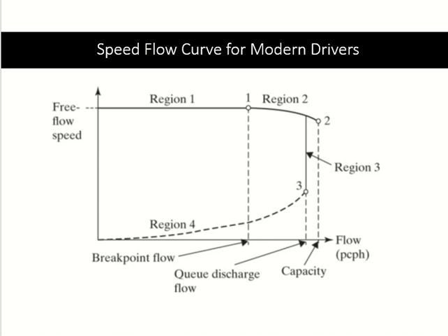To solve this issue, to make it much smoother, I don't have the curves for that, but in some countries they use variable speed limits or driver warnings. So before you reach that point, you will get a warning that there is a traffic jam ahead. They have LED screens showing there is a traffic jam. Even for variable speed limits, they use LED screens. There are screens on the road at specific points, and you see the screen. You don't see the queue in front of you, but you know that you will reach that point. So you may change your route.